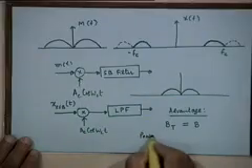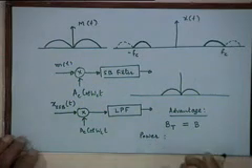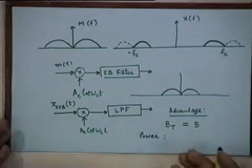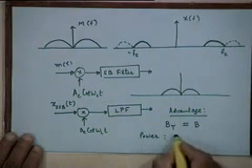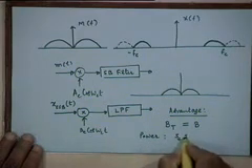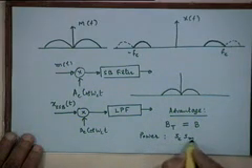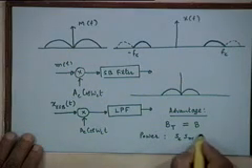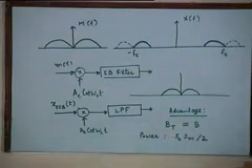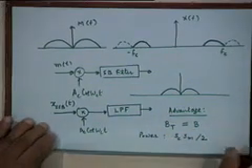That's the main advantage. What is the power that will be transmitted in the SSB signal? What was the power that was being transmitted in the DSB-SC signal? If you remember the expression, it was S sub C into S sub M, which was the carrier power into the message power. So in this case, how much will it be? Divided by 2, because you are removing one of the sidebands.